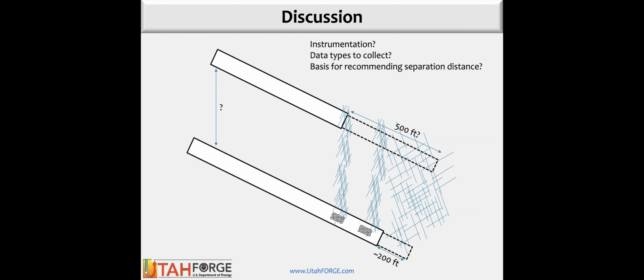From my preliminary CFD modeling on the perforations, there's a pretty high sensitivity. What I don't know, and I'm not convinced by some of the things in the literature for these crystalline rocks, is if we did a perforation cluster of, say, 6 shots per foot over 20 feet, so 100 perforations or so, how many of those are actually contributing to flow leaving the well?